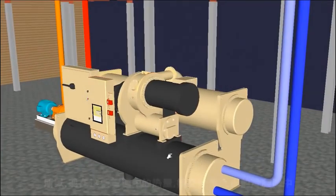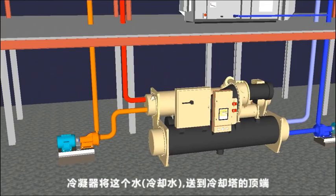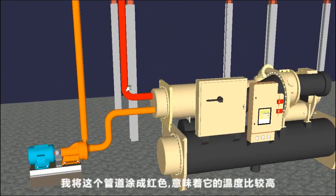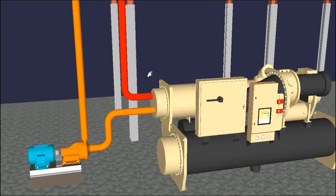So now that the heat in this pipe here has been transferred over to the condenser side, the condenser then sends this water, which is now called the condenser water, up to the tower. And in this instance, I've coloured this pipe red so that you know it's a higher temperature, and in this example it's about 35 degrees Celsius, at a flow rate of about 58 litres a second, being sent up to the cooling towers. That can change as it's just on this design for illustration purposes.